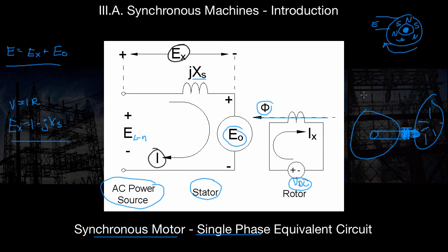This time, we're applying voltage E on our stator windings. The stator windings create a magnetic rotating field that attracts the rotor, so the rotor spins to catch up with the stator windings. Then we put on our excitation voltage, right? Our plus, DC, minus. That locks the rotor into place, so now we have two magnetic fields magnetically coupled. And since our mechanical load is physically connected to our rotor, it has to spin as the rotor spins. Does that make sense? So it's essentially a generator operating in reverse. So this is a motor.